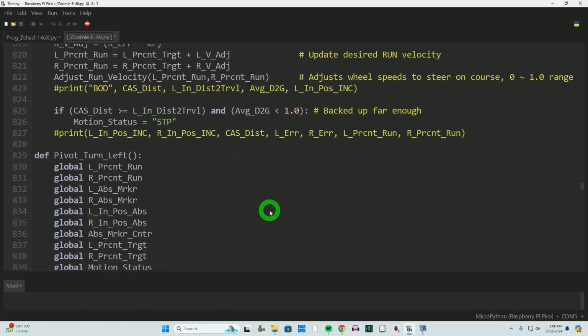When I back out and then I make that pivot turn, I want to be lined up on the guideline with my sensor. So that all has to play very tightly and very precisely. Early on, I kept emphasizing the importance of being able to position. My target goal was within 0.5 millimeter anywhere this thing moves. I don't think I'm ever going to achieve that goal, but I'm very close to it. And these are the different things that you have to do to achieve that precision. And hopefully I can get the rest of the little problems worked out.